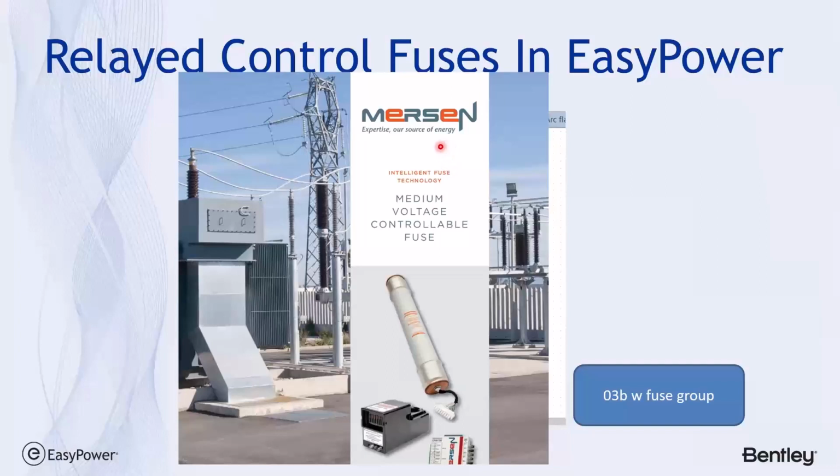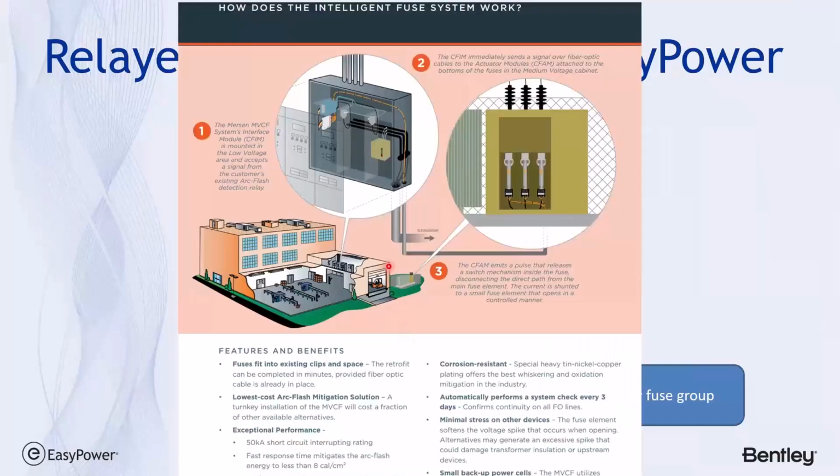I've just found the data sheet on the web, where Mersen provides, inside of a medium voltage fuse, 2 fuse links, with the ability to sense a downstream relay, an arc relay, the ability to trip open the normal connection and allow a current limiting fuse to be subjected to the fault current, and consequently you'll have a quicker reaction to an arc fault on the low voltage side than you would if you waited for low voltage arc flash protection.